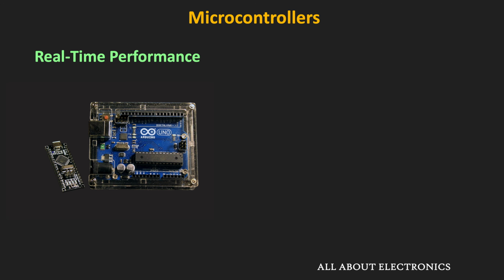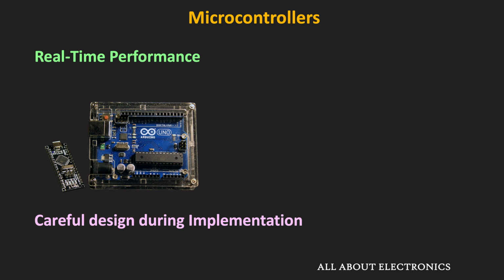Of course, current generation microcontrollers can also scan the inputs and update the outputs in the same order of microseconds to milliseconds. But for that, these microcontrollers must be carefully programmed to get this deterministic scan cycle. But in the case of the PLC, that is the inherent feature. Now, another major difference between the PLCs and the microcontroller is the operating voltage and the voltage range of the I/O modules.